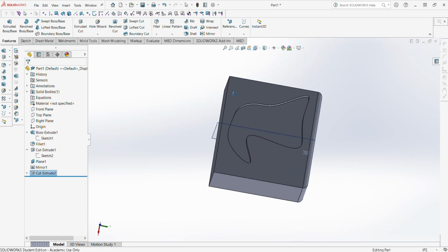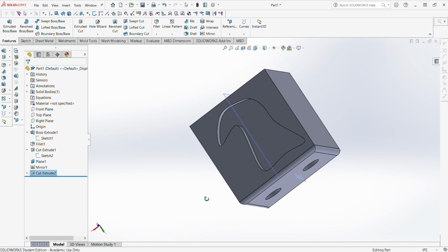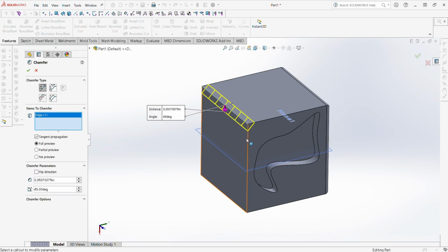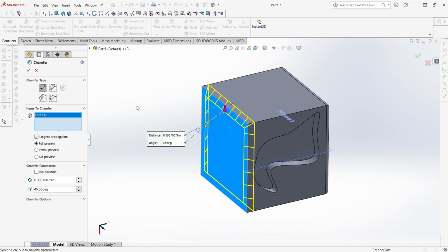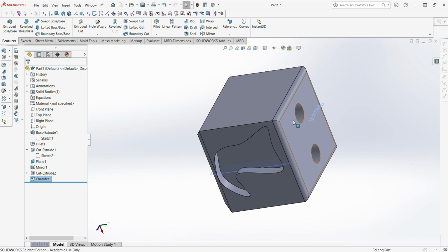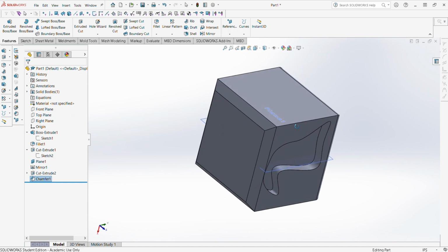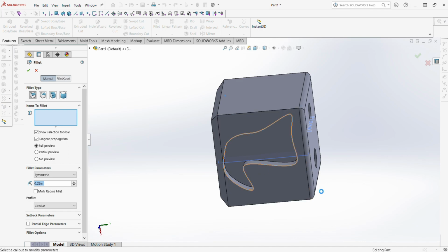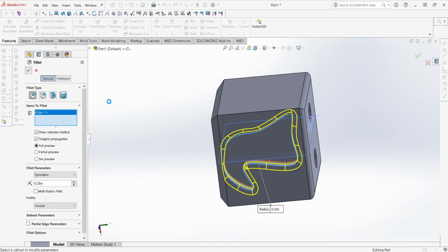So now we have our, looks like a sorting hat kind of deal. I'll show you what this chamfer looks like just so we have a cool shape. Oh, also, first thing, you can just click this surface and it'll chamfer all the edges. I know the last time on the fillet I clicked all the edges, but you can also do this and then it'll fillet all those.